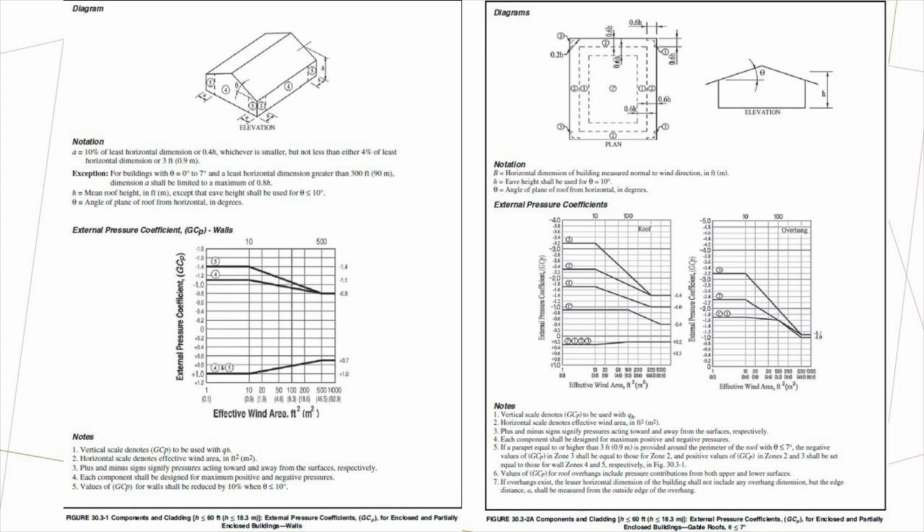After addressing parapet forces within the main wind force resisting system, we move on to components and cladding, which is governed by localized pressures based on tributary areas. Elements such as roof panels, wall panels, fasteners, and trim pieces fall under components and cladding design, and they often experience higher localized pressures than the global main wind force resisting system loads.